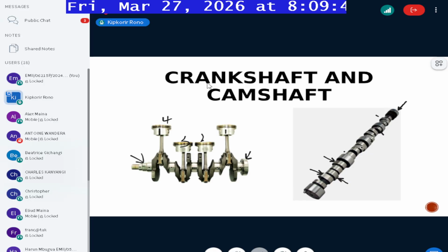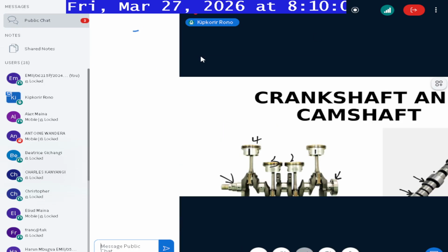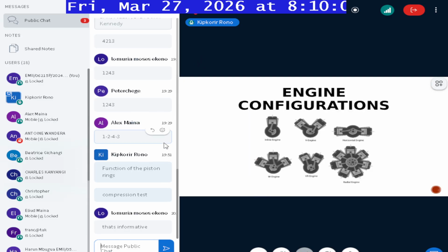I know for those who are working in mechanics, you can get it easily. Try and see if you can get the firing order based on the arrangement, if it's a four-cylinder engine, check the arrangement of all the cylinders and then see if you can get the firing order. It is so easy to do that as well. Okay, it's something that I've done so many times. It's very easy to get the firing order from the arrangement or the orientation of the cams along the camshaft.